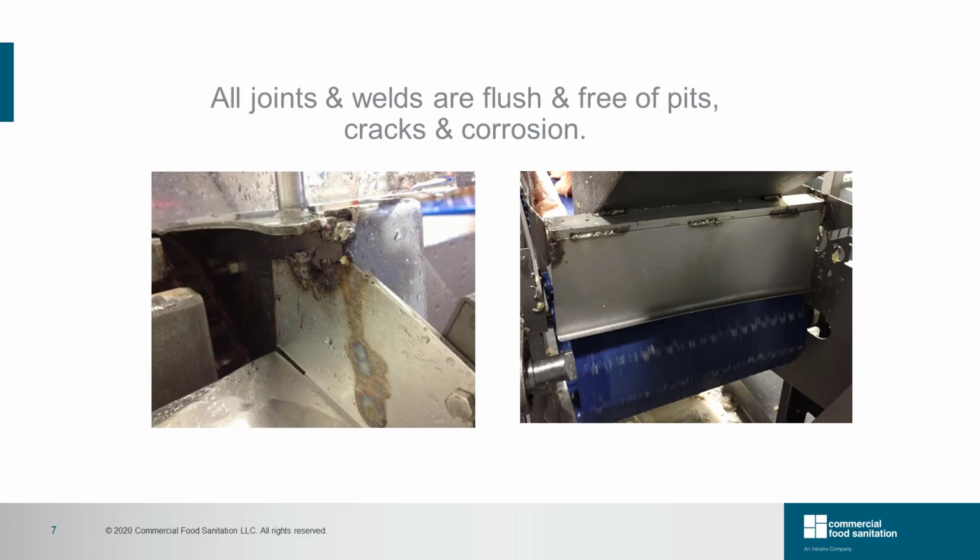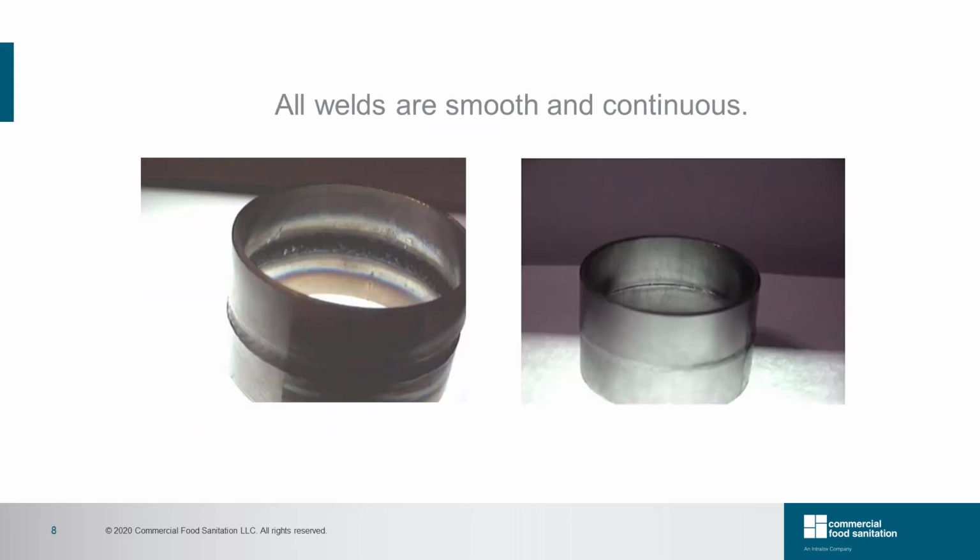The picture on the right shows non-continuous welding above a product area. Not only is the welded design unnecessary, a hard-to-clean spot is created behind the plate. A different design could have eliminated these welds and avoided creating a hard-to-clean spot. All welds are smooth and continuous.